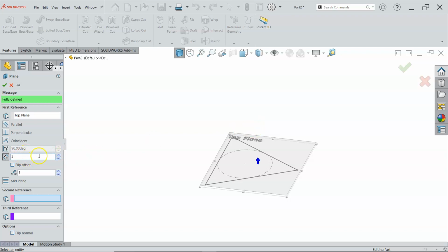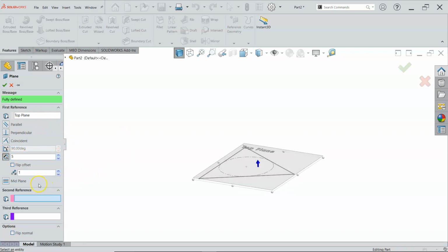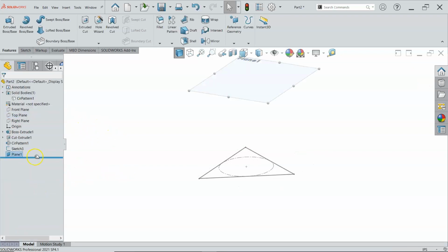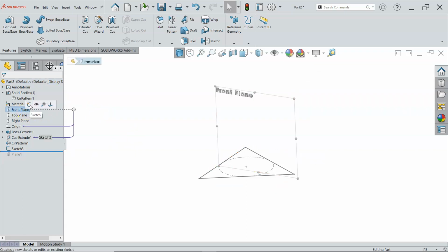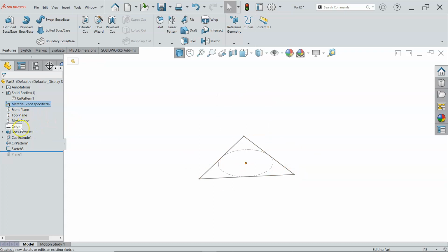I have kind of the same problem that I did with cutting the edges off, in that I don't really know where that plane is going to be located. So again, I need a construction sketch to help with making those angles even. So the front plane bisects the triangle, and will end up on the vertex at that side. And I open up the sketch.